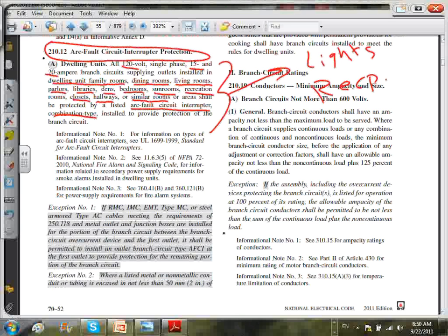When they created the arc fault circuit interrupter, guys, it used to look at the parallel arc, the arc between a phase and a neutral, or a phase and a ground. The electronics would look at only a parallel arc between hot and neutral, hot and ground. But what happens if you break the hot, the series? There will be an arc between this side of the hot and the other side of the hot. Not completely broken, but a bad connection. So they created the combination type, which looks at series and parallel arcs.